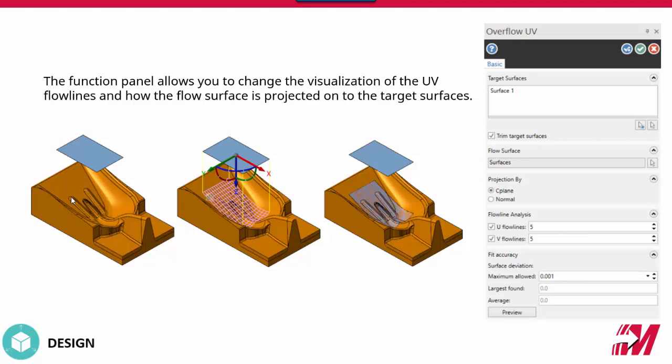So when you use a flow line and you window surfaces, one surface can cut one way, the next surface right next to it can cut 90 degrees from it. So you don't get this nice flowing motion of a toolpath.